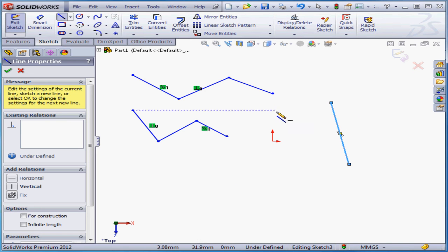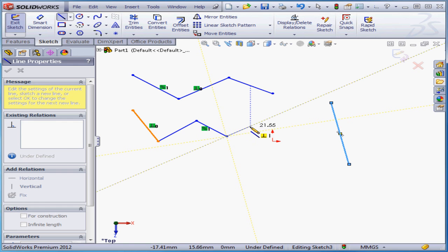Next, let's create a line between 2 points. Let's mouse over this point. This double yellow circle is the coincident relation glyph. When a relation glyph is visible and I left-click the mouse button, I will apply that relation at that point. I've just applied a coincident relation between the 2 lines at that point. Once again, we've got the rubber band effect and feedback.